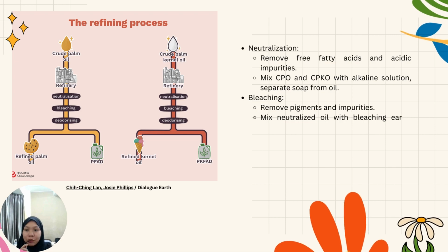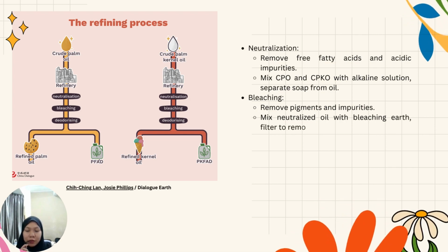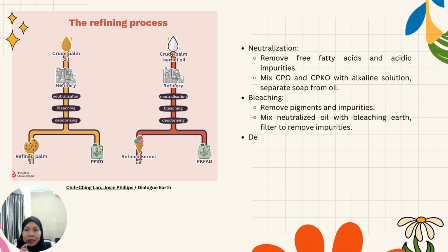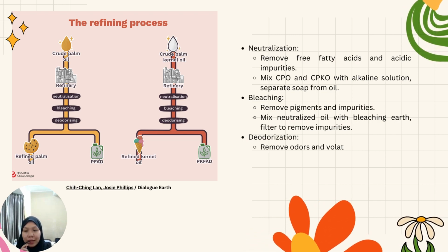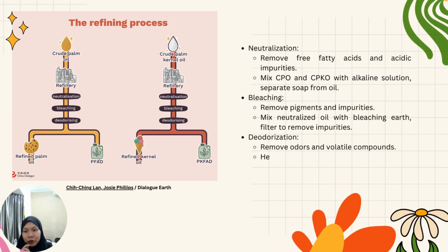The neutralization process for CPKO is similar to that of CPO. However, CPKO typically contains a higher level of free fatty acid compared to CPO, so a higher concentration of alkaline solution may be required for effective neutralization.